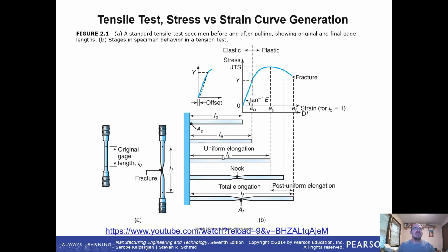As far as that's concerned, that uniform elongation happens until this point. And then you end up getting a plastic stretching. So elastic, you get an elastic stretch here. And I think I mixed those up. So this would be uniform elongation to here, if you don't have any necking. This is our elastic elongation. So for elastic elongation, our elasticity point is right at our yield point.